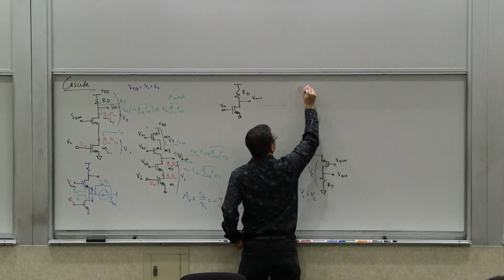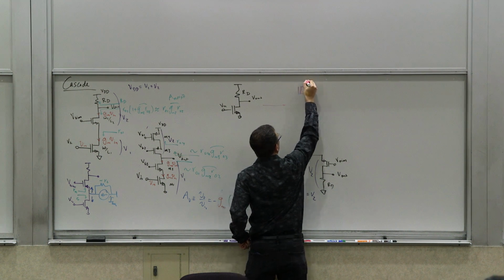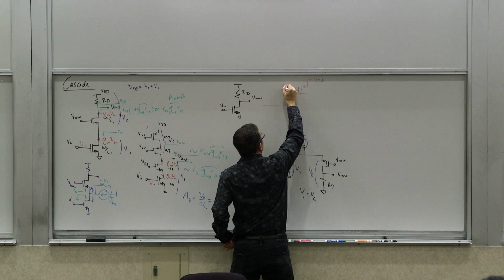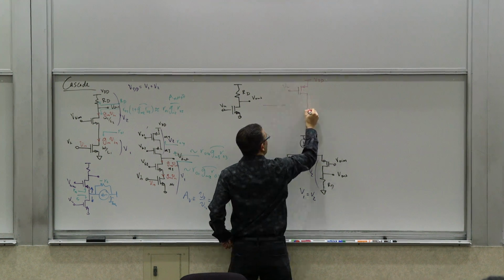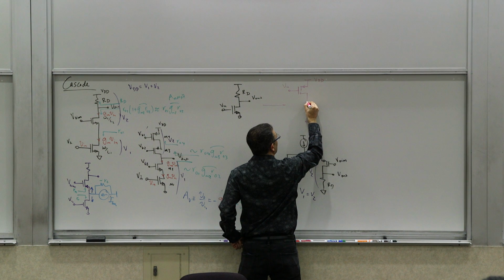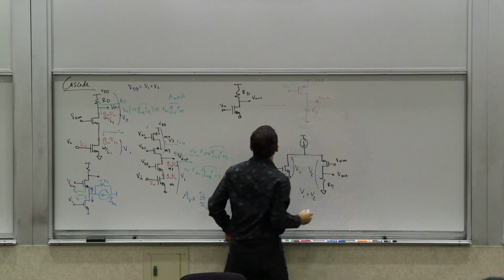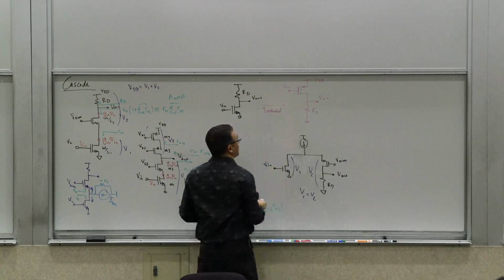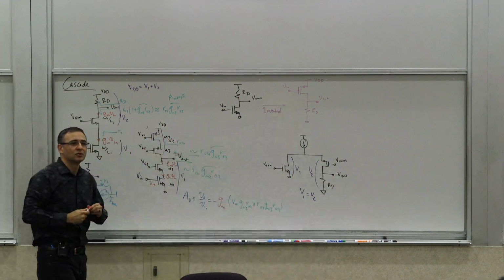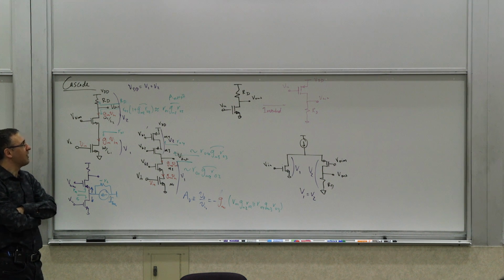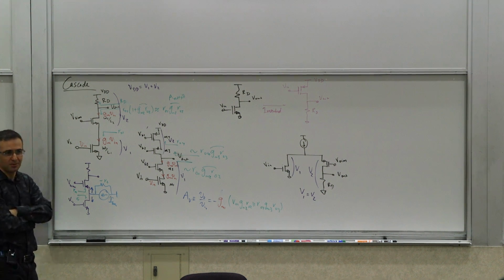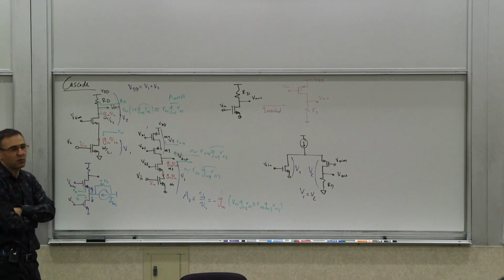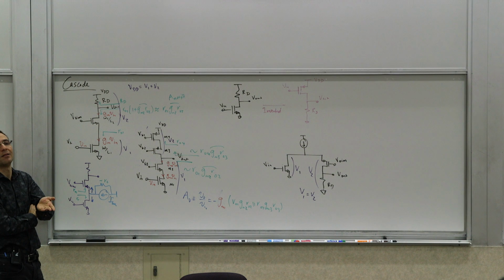And now remember, for a P-type device, the source has to be at the highest potential. So we have a VDD here. Now, this would be my input, Vin. And the load now needs to be referenced to ground. So this is the inverted, or upside down, version of it. So essentially, if you have complementary devices, if you have a P-type for every N-type that you have, that's not much worse. If it's much worse, you can still do that, but that stage will not perform well.